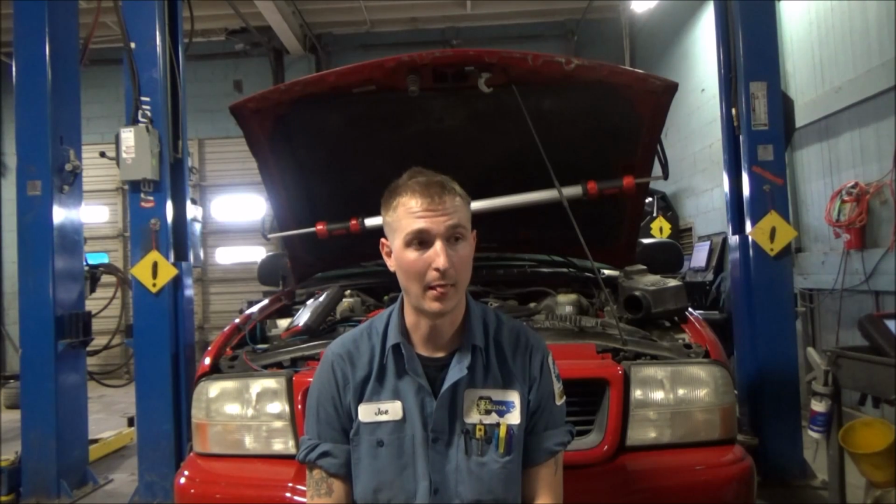Troubleshooting this, very simple. It's a 3-wire potentiometer. We have a 5-volt reference, a sensor ground, and a signal wire. We identified that this signal wire is a pull-up design, so this sensor is actually sending voltage to the engine computer, not the other way around. So we got to be a little bit creative when we're thinking about doing wiring integrity tests on this design circuit. It's not as easy as just unplugging it and verifying that we have 5 volts there.